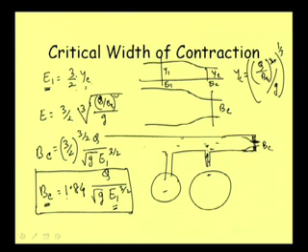So, when we know the width of the section here upstream, B1 is known, as we know the Q, we know the Y. So, we can calculate E1, and then we can see Q is known. So, we can calculate all this part, and then we can see what should be our BC. And if we want to have critical flow condition here, we should make the width equal to BC, then only we can get critical flow condition.